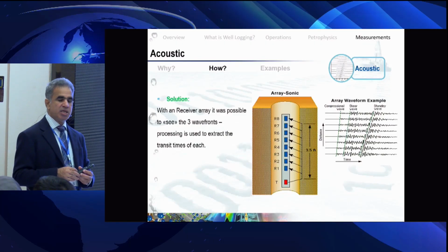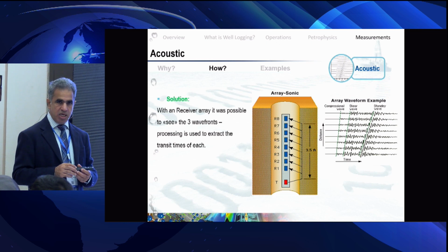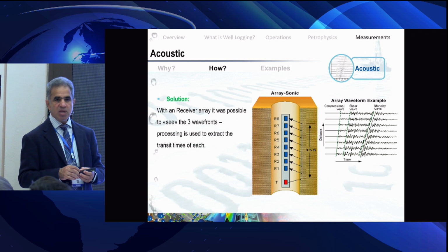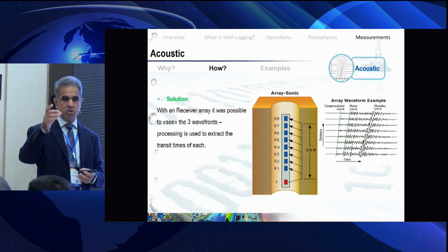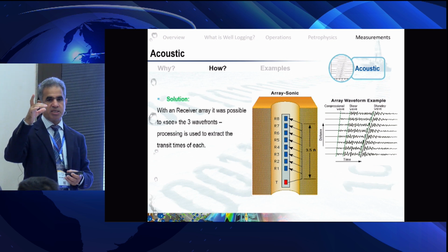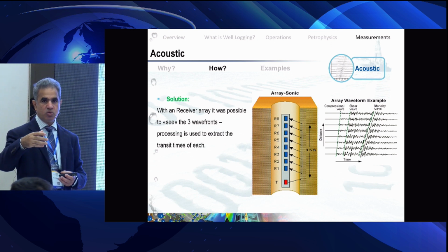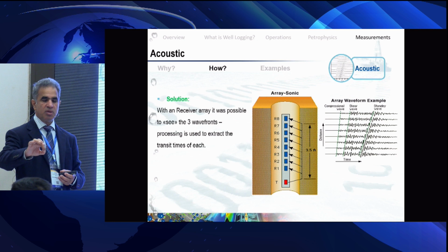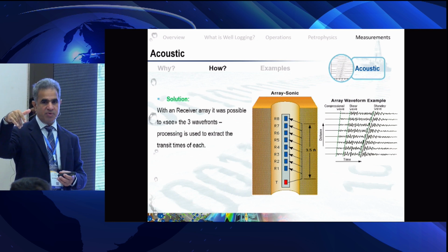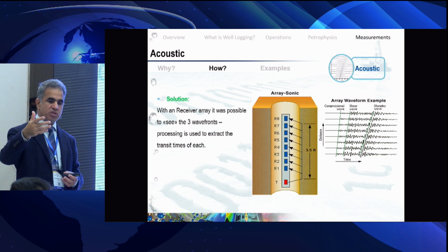No, in deviated horizontal we can use the same tools. The conveyance is different. In a vertical well, or in a low deviation, the tool basically goes by its gravity. The tool weight pushes the tool into the borehole. If you keep increasing the angle, the gravity will not work. So it means you need an extra, external force to push the tool downhole.